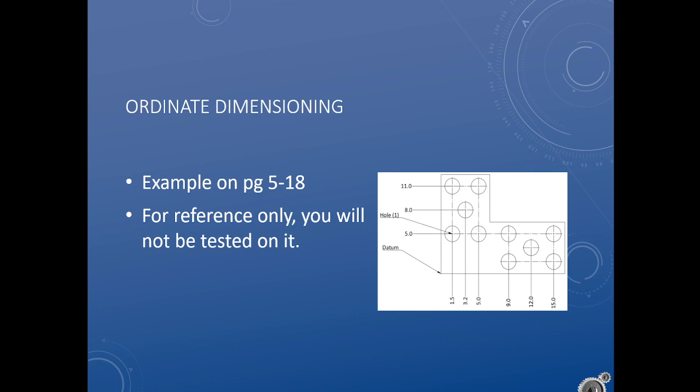And this is just a quick note that there is yet another kind of dimensioning that we haven't looked at called ordinate dimensioning, where we just drag off individual numbers, and this is an indication of how far we are from the datum. You might see these more in architectural drawings and plan views rather than manufacturing drawings, which is our focus.